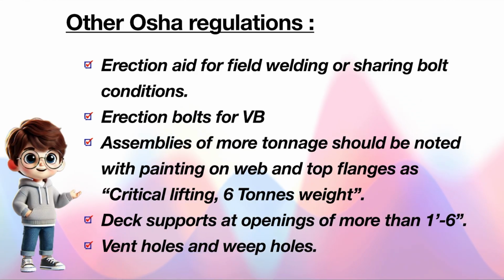Now there will be different crane capacities that erectors use at site. It varies from project to project, meaning it varies depending on the size of the project. Let's say the erector's crane capacity is 6 tons. Then his preferable handling weight is usually 4 tons.